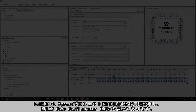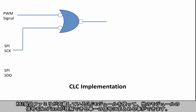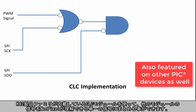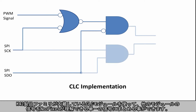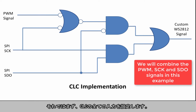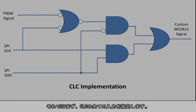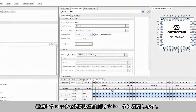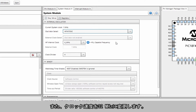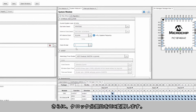I have my MPLAB Express project configured for the PIC18F46K42 and my MPLAB Code Configurator opened. The configurable logic cell peripheral featured on devices in the K42 product family can be used to combine other peripheral signals into a single signal that the Neopixels can understand. We will first start by configuring all of the inputs for the CLC. I will start by changing my clock to high frequency internal oscillator. I'll also change my clock speed to 32 MHz. Additionally, I will change my clock divider to 1.